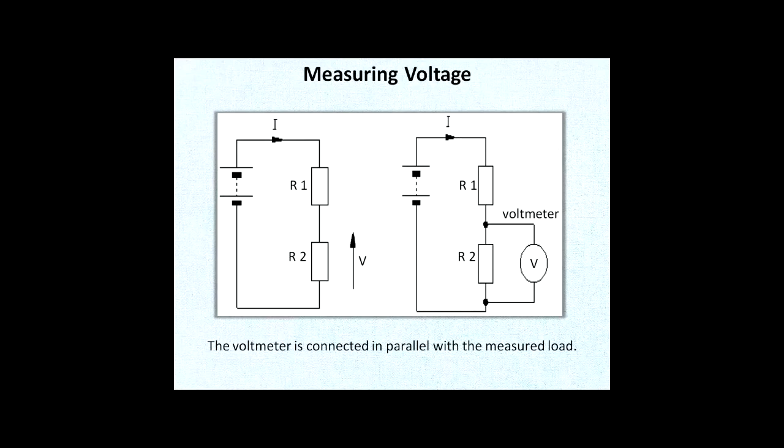If you stick to that way of connecting circuits, it's going to be much easier for you to either connect the circuits or verify if somebody has, because sometimes in different subjects in my classes, I used to have two people. One person is assembling the circuit and the other person is going to verify. So if you verify the circuit, you're just going to verify the current path first and then make sure that the parallel devices are connected to it, okay?